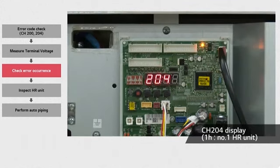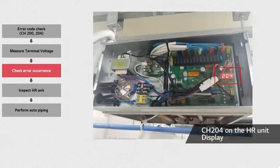You can also check if it is error CH204 by taking a look at the screen of the ODU's PCB. Remember, this is a communication error between the ODU and the HR unit. As shown in the picture, you can also check the error at the HR unit's 7-segment display.